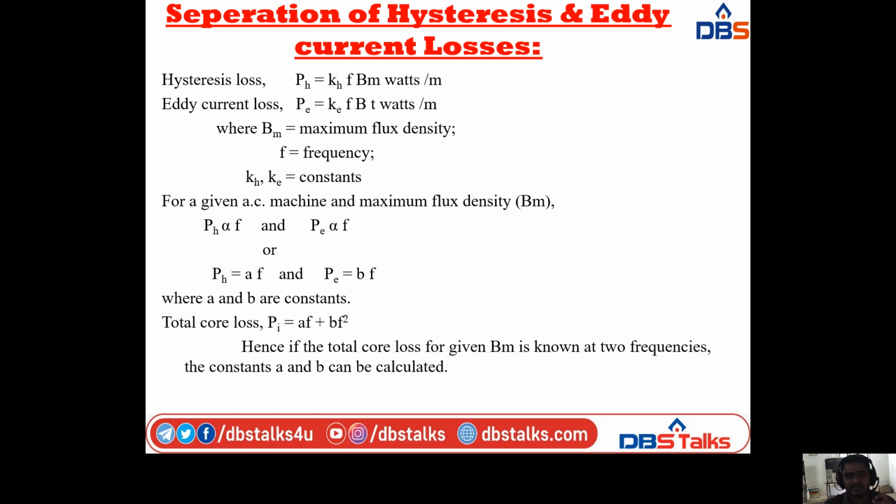For a given AC machine, that is nothing but a transformer, and a given maximum flux density Bm, the hysteresis loss is directly proportional to the frequency, from the equation of the hysteresis loss, P sub H equal to Kh into F into Bm.